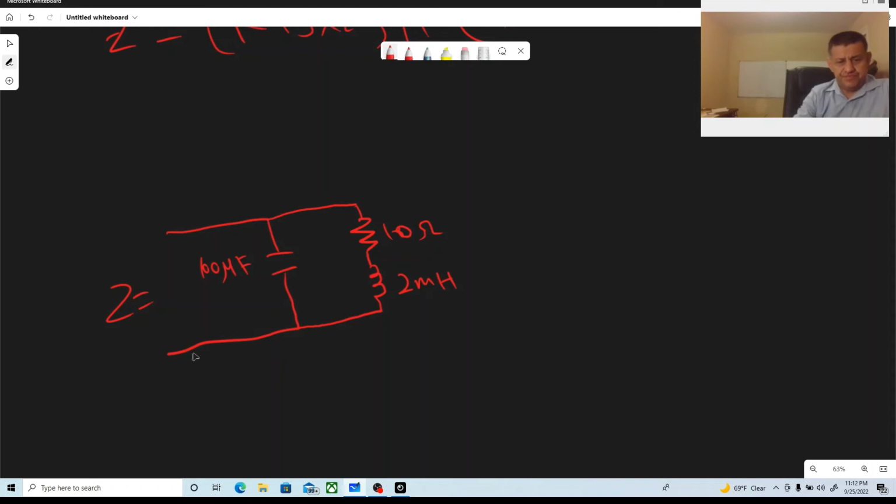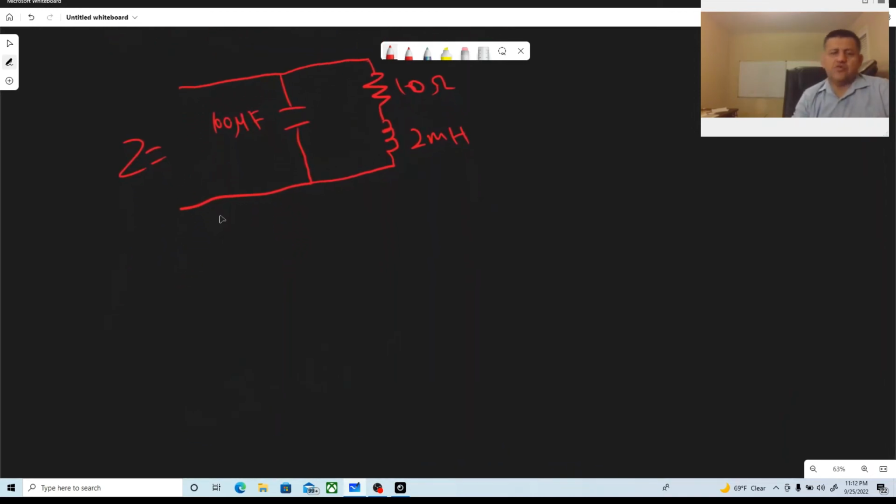Now, let's do this step by step again, so we can find XC, which is equal to 1 over omega C. We know that omega is 2 pi f. Frequency is 60, and you multiply by 2 pi, it's equal to about 277. I'm sorry, 377.